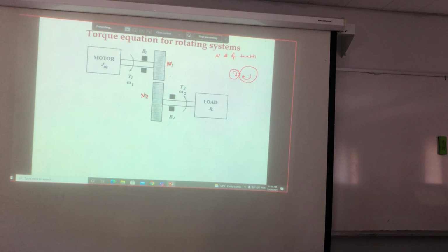Now, if the robot arm hits any object, and there is a gearbox, you cannot sense it, or it's hard to sense. But if there is no gearbox between the end effector, let's say, and the motor, you can simply sense the torque. There's an action torque, and automatically this will prevent damage to the object. So this depends on the application. For regular applications, such as a train or elevator, of course, we need a gearbox in order to regulate the power.